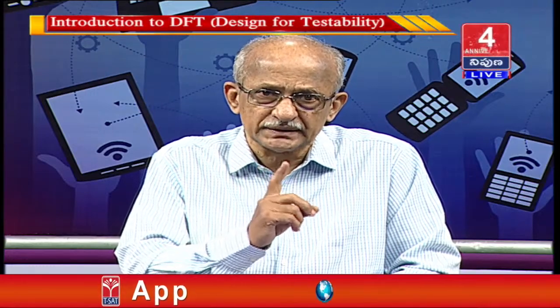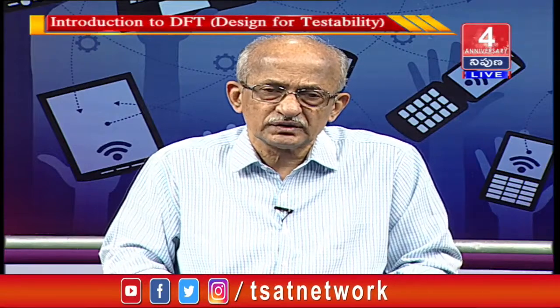There will be one memory having a large depth, let us say 4 megabits of memory per pin of the package of the part. That means every time you have to apply a pattern, it depends on the number of input pins. If you have 100 input pins, you need to have 100 bits coming and getting applied to these 100 pins.